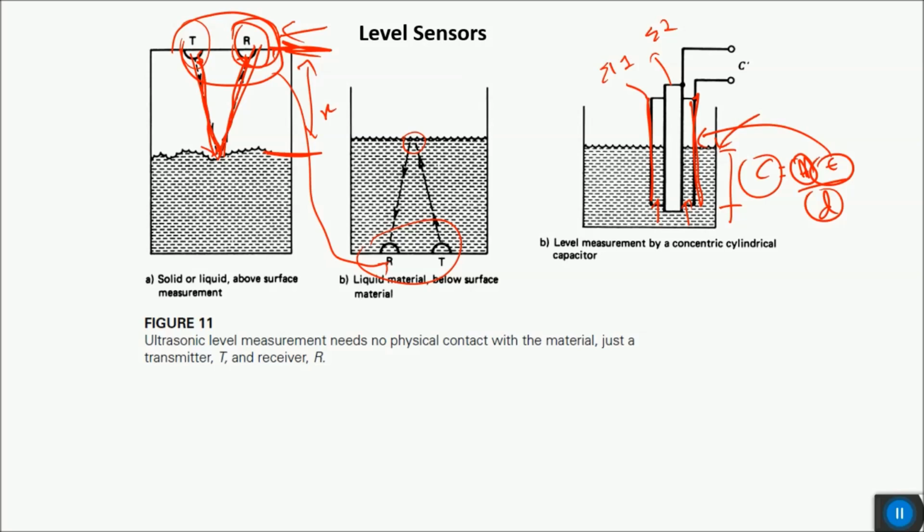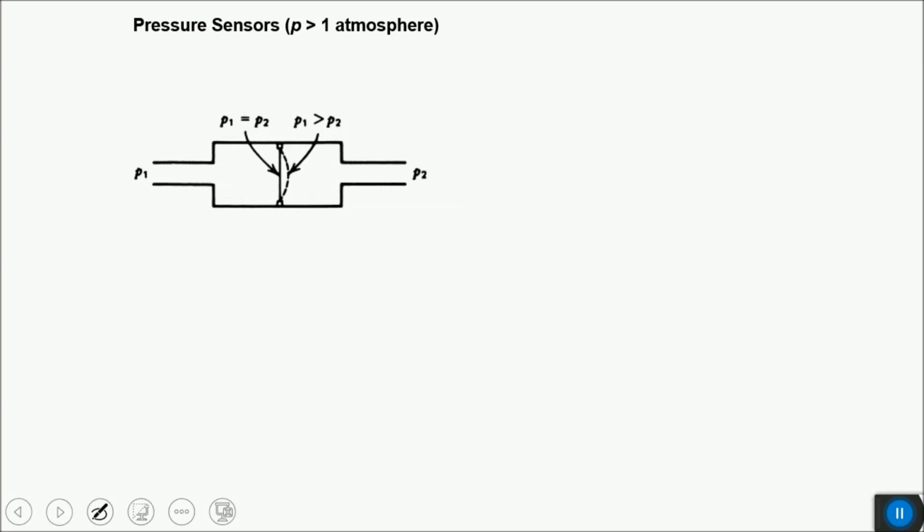There are further approaches that can be used to measure the water level. One can be resistive. We can have a printed variable resistor here, and this water can be used to change the resistance of this printed longitudinal resistive sensor, and that change in resistance can be converted into the change in water level.